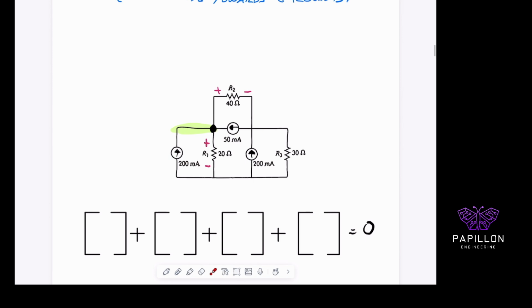Okay, so the next thing to do is to make an observation about your node. So here's my node, right? This little giant black ball. And I look at the branches that I have with my circuit for that particular node. So this junction, where I were to solder it, let's say, I'd have this branch here, another branch here, that's 2, a third branch here, which is 3, and a fourth branch here, which is 4. So my KCL equation, right, it's going to be 4 branches, 1, 2, 3, 4, all of them summing up to be equal to 0.